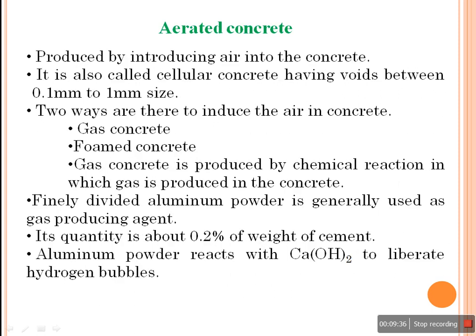Next concept is aerated concrete. It is produced by introducing air into the concrete. It is also called cellular concrete, having voids between 0.1 mm to 1 mm in size. There are two ways in which you introduce air into the concrete, that is gas concrete or foamed concrete.